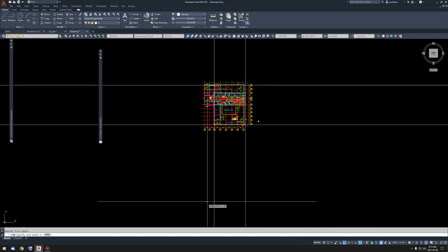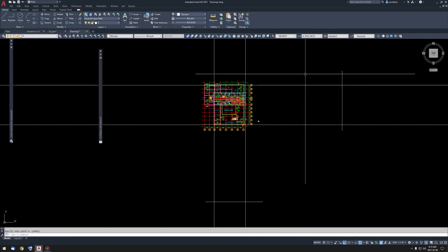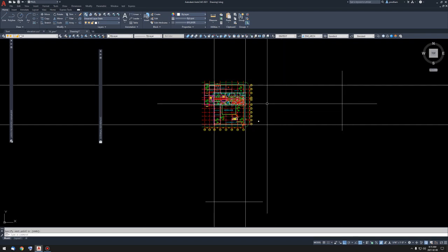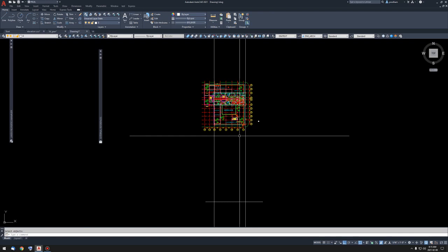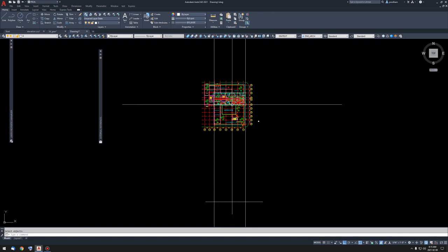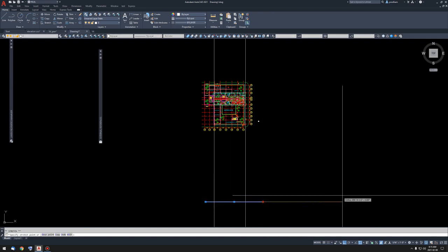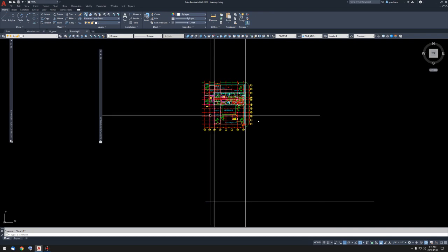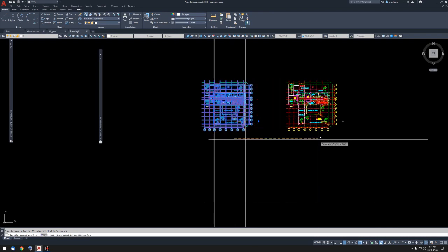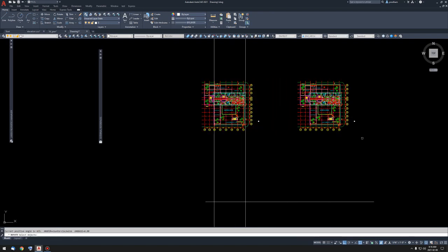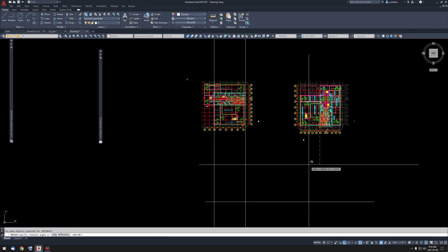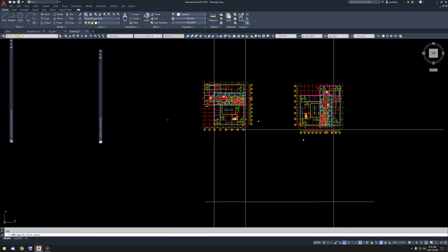Now, we're only doing the north, we're only doing the west, we're not doing the east, and we're not doing the south. Okay, but here's the thing. We're not going to do the pinwheel system. We're going to project it down for this plan. These plans are going to project down like this. And then if you think about it, another big advantage of this way of doing things as opposed to the pinwheel is I'm going to copy these XREFs. Just copy them over anywhere and rotate them so that they're now facing the west, like that. Now what I can do is project my lines down like this.